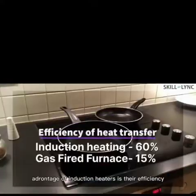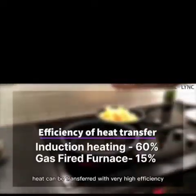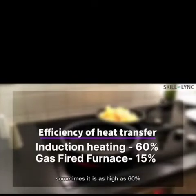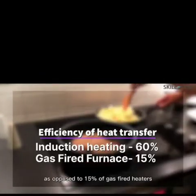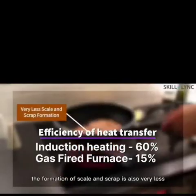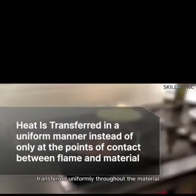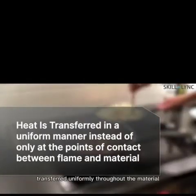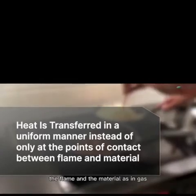The biggest advantage of induction heaters is their efficiency. Heat can be transferred with very high efficiency. Sometimes it is as high as 60% as opposed to 15% for gas-fired heaters. The formation of scale and scrap is also very low in induction heaters. The heat is also transferred uniformly throughout the material instead of only at the points of contact between the flame and the material, as in gas heaters.